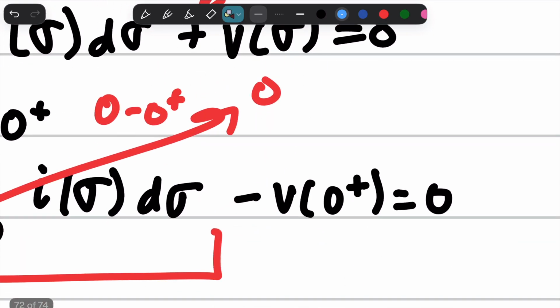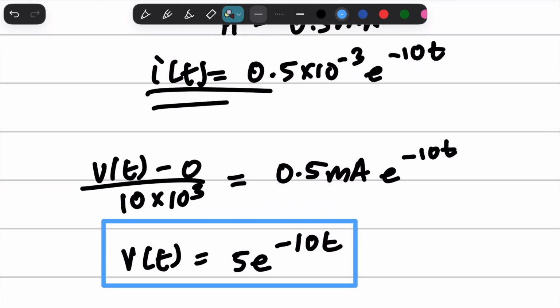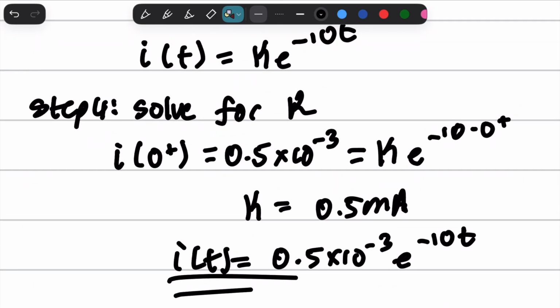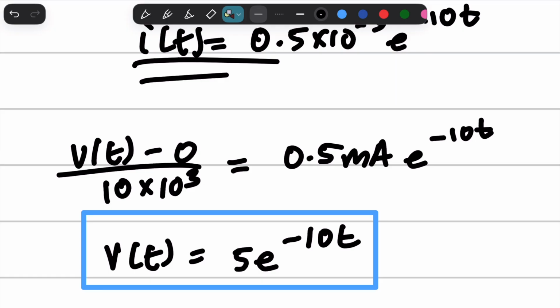Because of this right here, you could get it wrong, and I've gotten that wrong so many times. And then you have to come up with an Ohm's law equation right here to find the same thing. But if you have extra time on your tests or you want to check with your homework, this is the best way to do it. And it also helps you practice your loop analysis.